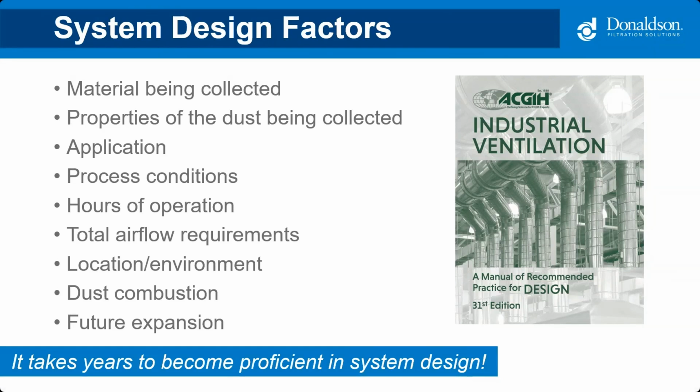Do they have compressed air available? Does the collector need to be located indoors or outdoors? What's the footprint and height requirements to make sure it can fit? Has the dust been tested for combustion or flammability? If it is, what's the NFPA standards that apply? And does the plant have expansion needs that we should consider when we first design the system? So as you can see, there's a lot that goes into designing a system.